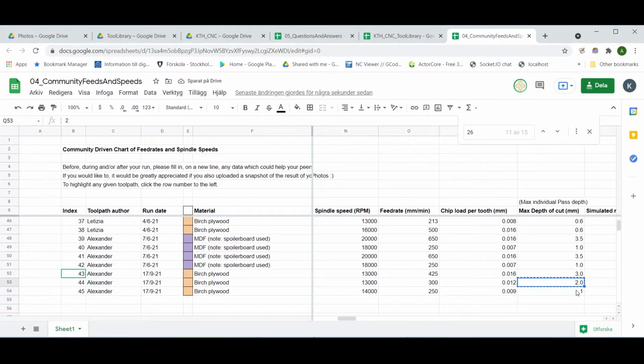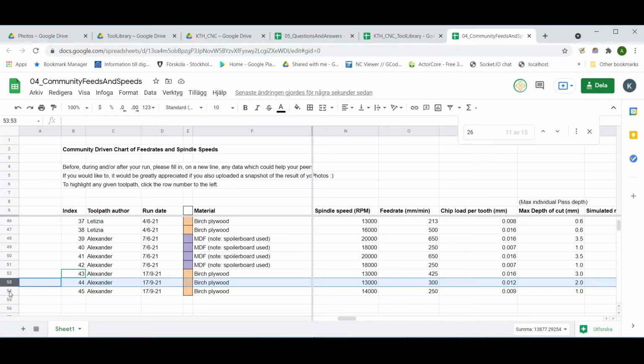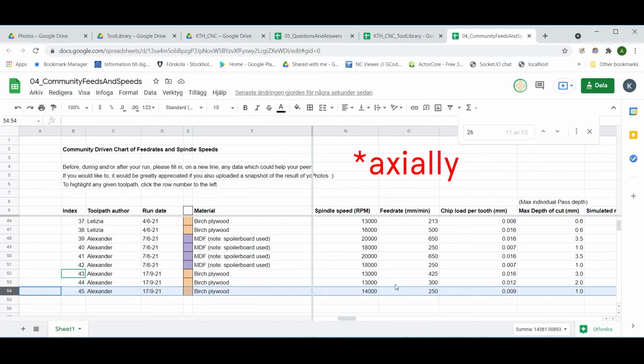And actually this will be per definition, since what we left in the settings for the roughing toolpath was exactly 1 millimeter radially. And for this parallel toolpath we will be milling all that is left in one go. We will not have multiple passes. Multiple passes can also be defined if one decides so. But for this particular example, we will use one pass of 1 millimeter. Very good. And there we have those settings defined that we need to input in Fusion 360.